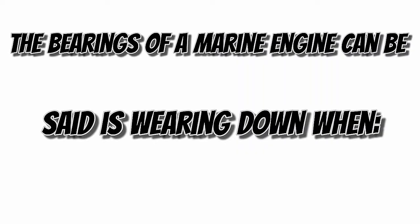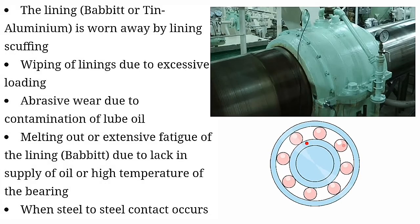The bearings of a marine engine can be said to be wearing down when the lining, babbitt or a thin aluminum, is worn away by lining scuffing, wiping off of the lining due to excessive loading, abrasive wear due to contamination of lube oil, melting out or extensive fatigue of the lining babbitt due to lack of oil supply, or high temperature of a bearing when steel to steel contact occurs.